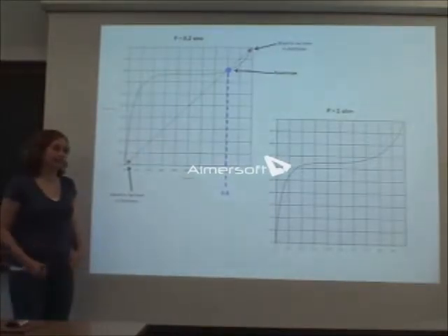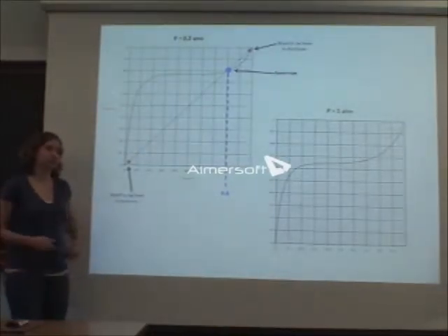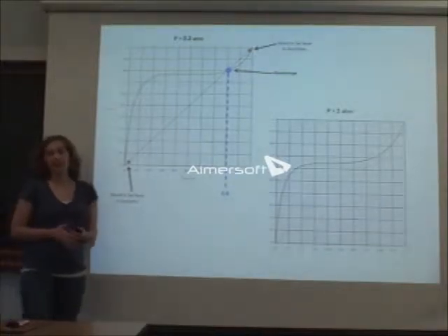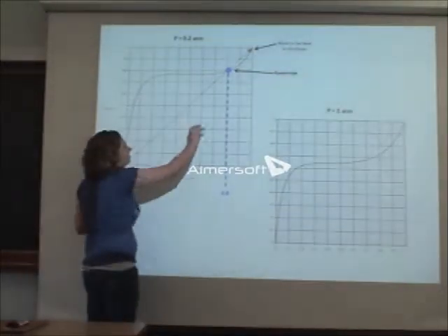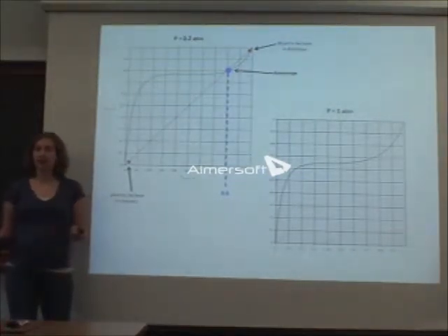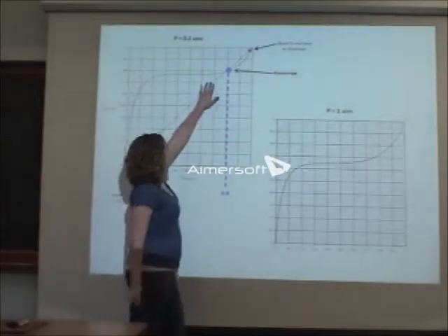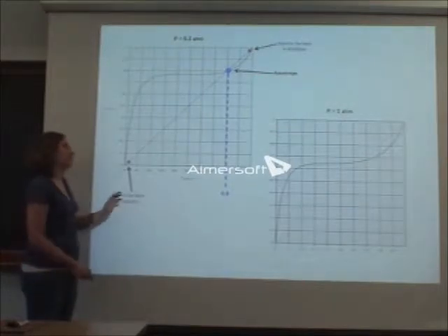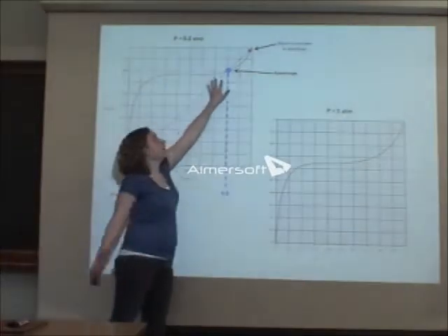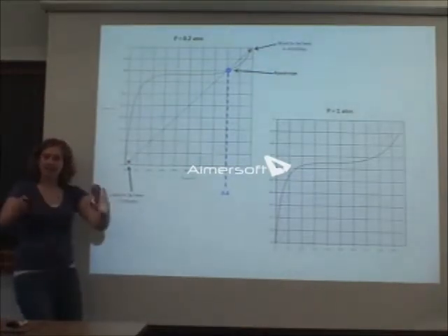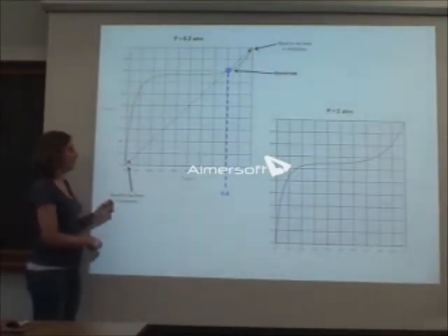Yeah, well. It means you have to have an infinite amount of equilibrium stages just to get there, and then a couple more to get to the start of it. Yeah, a couple more than any to get anywhere past that. So what does that remind you of? What else do you need an infinite number of stages to get past? A pinch point, right? So that's one thing that I like to think about when I'm looking at that: it's going to take me infinite stages to get to that azeotrope. So I'm not going to be going up here and then getting past that. There's no way to draw that nicely so it works. It's not going to happen, okay?